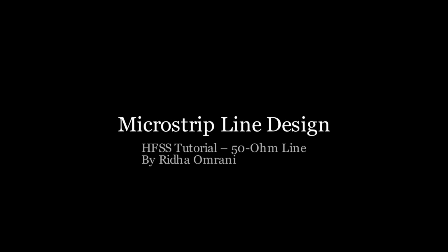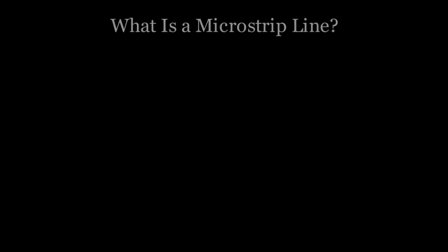Today, we are going to learn how microstrip lines work and how to design a 50-ohm microstrip line for HFSS simulation. This introduction will give you all the theoretical background you need before starting the HFSS model.